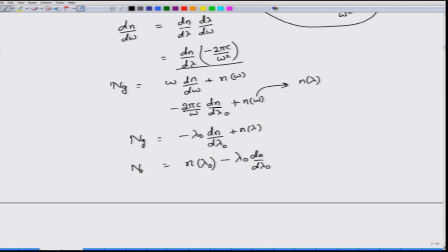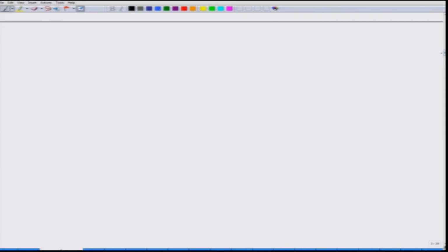Okay. So, as long as the refractive index is changing with respect to wavelength, you have a group velocity which is dependent on lambda, and this change in group velocity, dependent on the particular lambda propagating through the fiber, causes material dispersion and pulse spreading. Okay. The other dispersion that happens is the chromatic dispersion. So, here you have beta as a function of frequency omega, and this is purely because you have a waveguide structure.